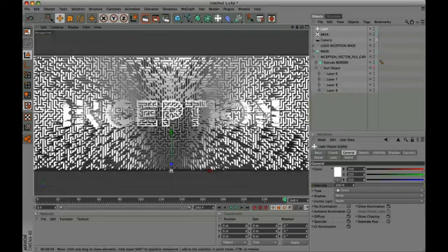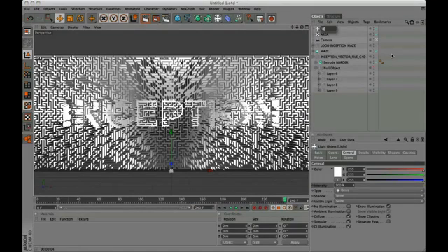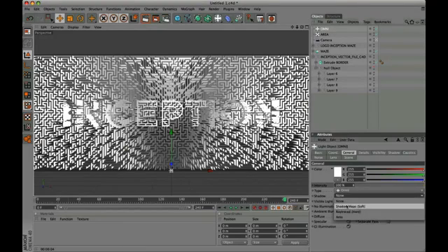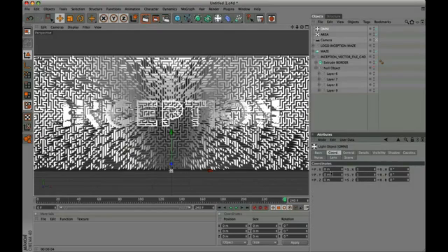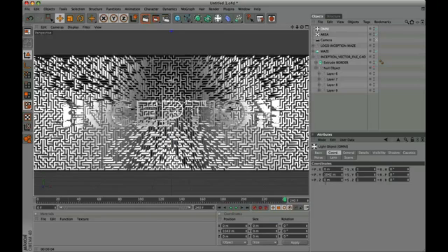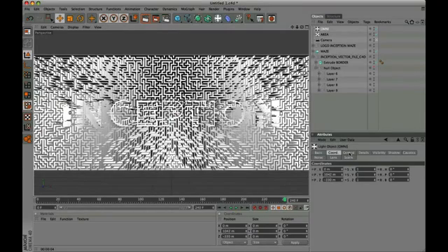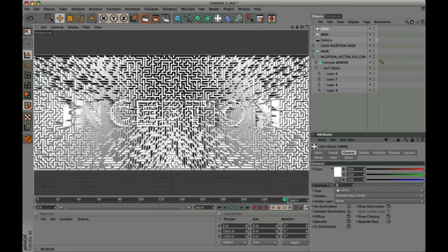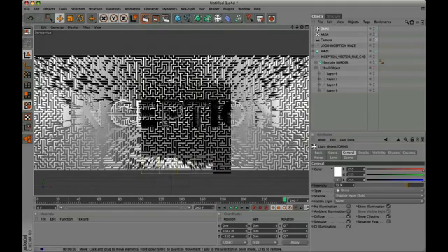Insert a new light, type Omni. Activate shadow maps, and insert the coordinates Y 1042, Z minus 330. Lower the intensity to 75. We make a render to see the result.